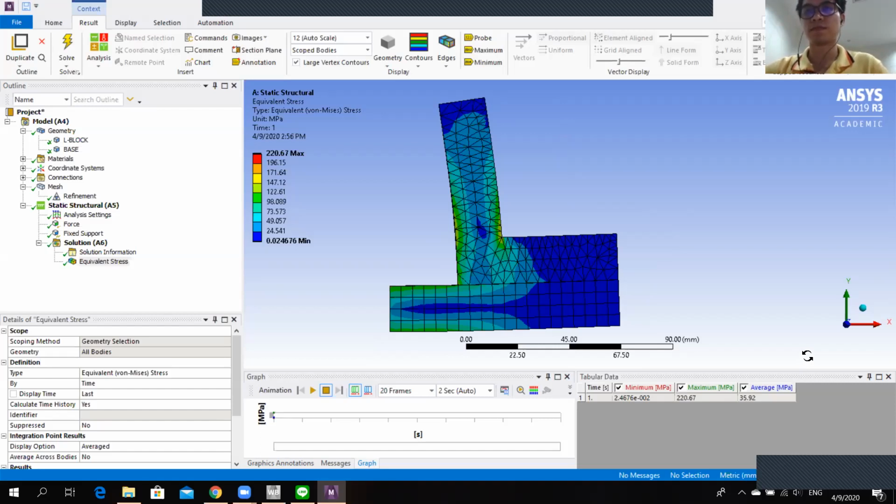And if you just look at the deformation of the L, they both bend up together, right? On the left side you see a short, pretty soft bending beam, then suddenly it becomes 8 times stiffer than it was before. And the same for the vertical part. It's pretty flexible, but then it meets the bit that is completely stiff. So that big jump in stiffness should, in my expectation, increase the local stresses we have on the inside of this aluminium part.